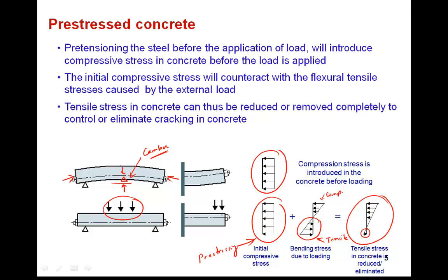Also in the cantilever, the second example, as you can see, due to this initial compressive force, the beam is bending upward, and when the external load is acting, the deflection is actually maybe even zero or very small.